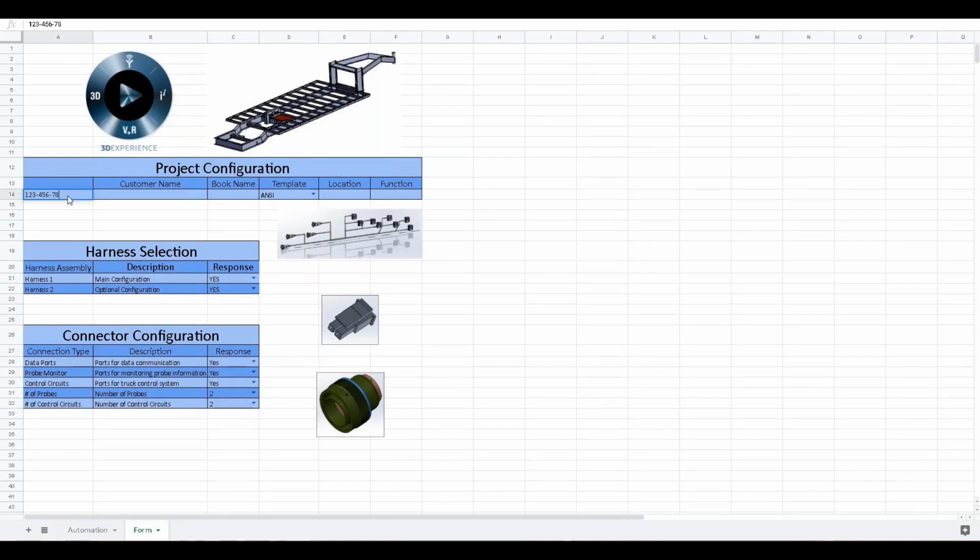What you're looking at now is a front-end form, an example that I threw together, where I am going to configure this particular harness arrangement for this trailer package based off of settings that I defined inside of this spreadsheet. We use a lot of information, macros, right? Circuits, reusable circuits, symbols, and the attributes to facilitate this level of automation.